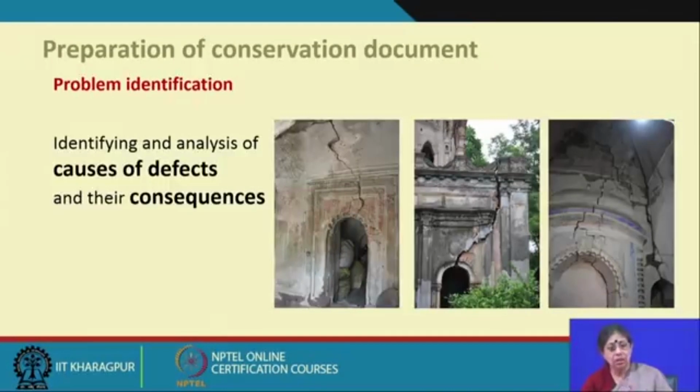be seen, it has to be tested and analyzed, depending on the case. The recording of the cracks and the monitoring of the cracks, understanding the crack and what the causes of the cracks are, has to be really understood. Until and unless we diagnose and remove the cause, we really cannot take any solution by just filling up the crack. We mentioned telltale.